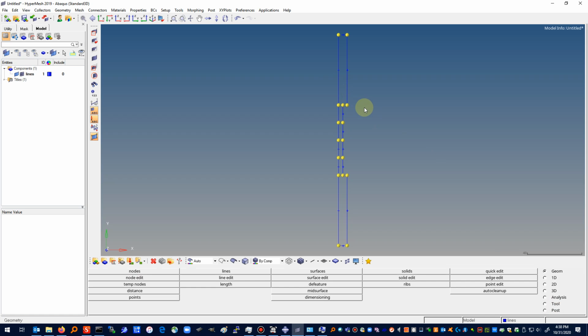And I'm going to use a 1/2 inch radius of curvature. We'll see where we want the center of this to be. I think we're going to move the center out here about a 1/2 inch or so. Might not quite be a half, or what did I say, a 1/4 inch radius of curvature. I guess I did say 1/2 inch radius of curvature. It might not be quite that, but we'll get something that looks nice. It's not going to be an exact ASTM type specimen, but it's pretty close to what we have our machine shop create. Alright, so for the radii of curvature, let me make a new component.